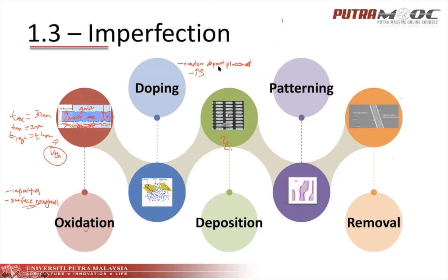Irregular surface. Okay, very good. So deposition process can also introduce irregular surface. What kind of parameters could be affected when you have an irregular surface? For doping, it will change the threshold voltage, so the threshold voltage will be varied. How about the deposition process?